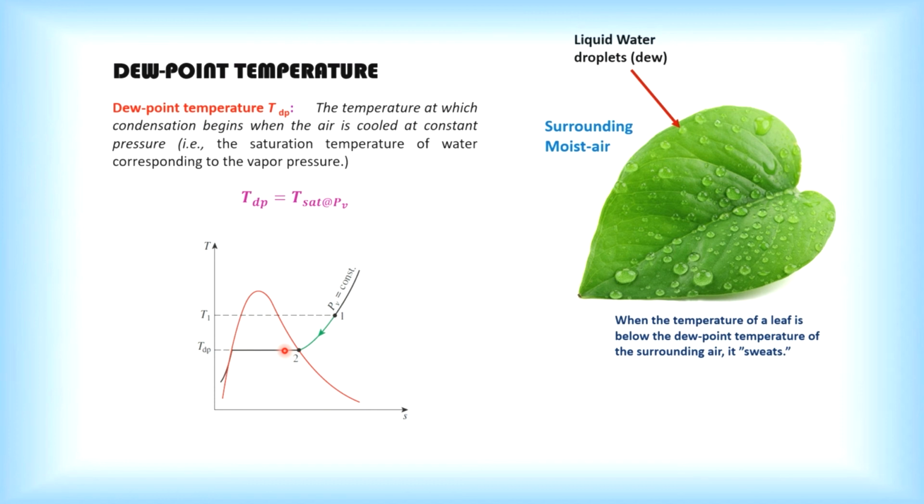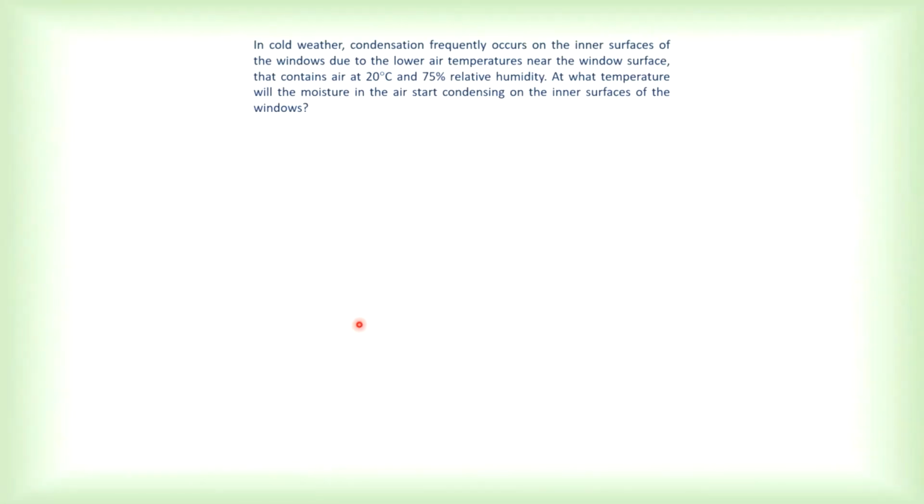That is wet vapor, which is the mixture of dry vapor and liquid. So you have condensate, or water being pressed out, squeezed out from the air, which we call dew formation. This is constant pressure cooling of moist air. Remember, the surrounding pressure is atmospheric pressure, which is 1.01325 bar at ground level.